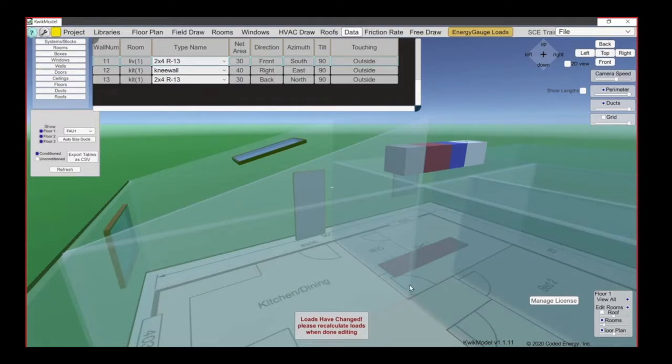And so the metal studs went all the way through this wall, and then they protruded up into the attic. And the back side of these metal studs were exposed to the attic. And if you can imagine attics in Las Vegas, they get pretty hot in Las Vegas, and the heat was heating up that metal stud, and you could actually feel it through the sheetrock down below.